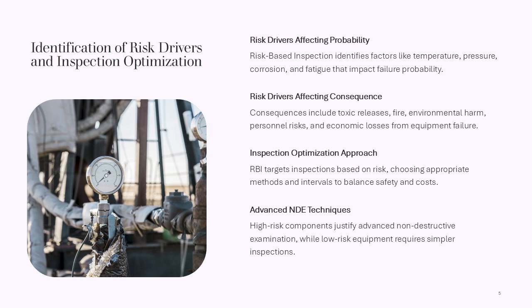For example, advanced non-destructive examination (NDE) techniques may be justified for high-risk components, while lower-risk equipment may require less frequent or simpler inspections. This targeted approach avoids overinspection, reduces unnecessary exposure of personnel, and ensures that inspection budgets are spent where they provide the greatest risk reduction. In this way, RBI serves as both a risk management and cost optimization tool, supporting sustainable and defensible inspection strategies in complex engineering environments.